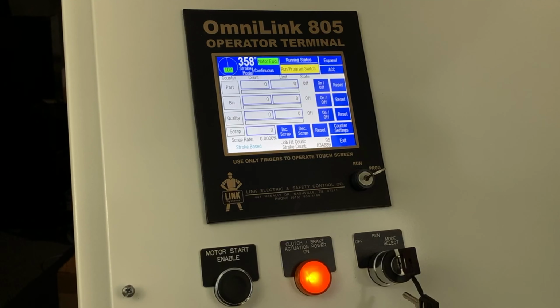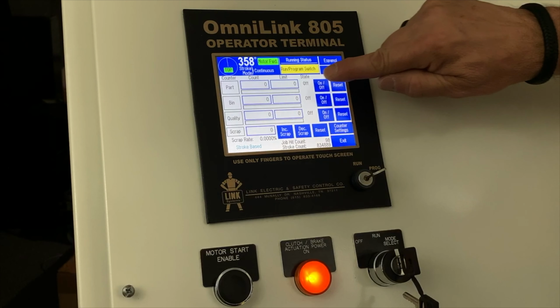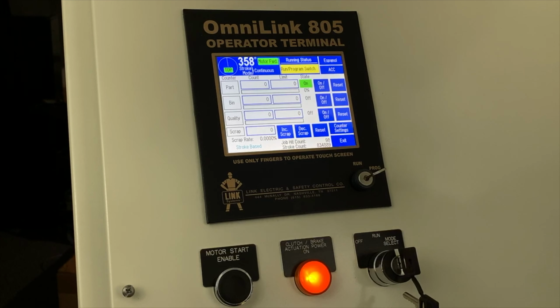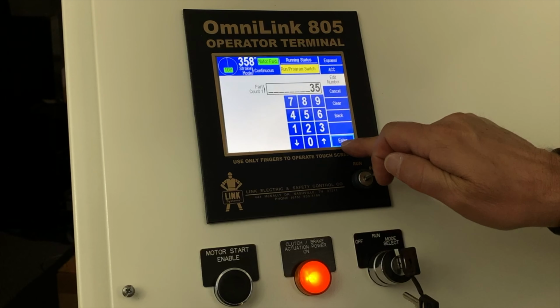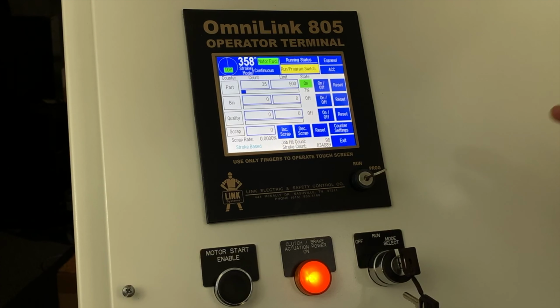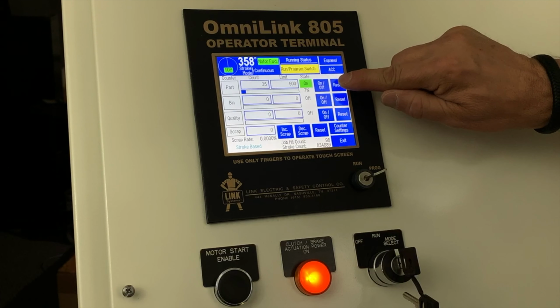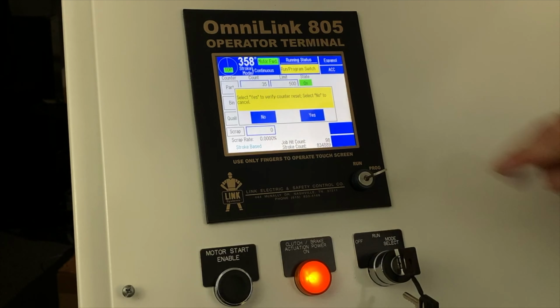In each of the counters, you can select the number already completed and the max limit for this style of counter. The counter must be on in order to count. If by accident you have cleared the part counter in order to run, say, a hot job, you can enter back the number previously completed in the first field. Part count is the example here. Once you arrive at the count, you will need to reset the count in order to continue.